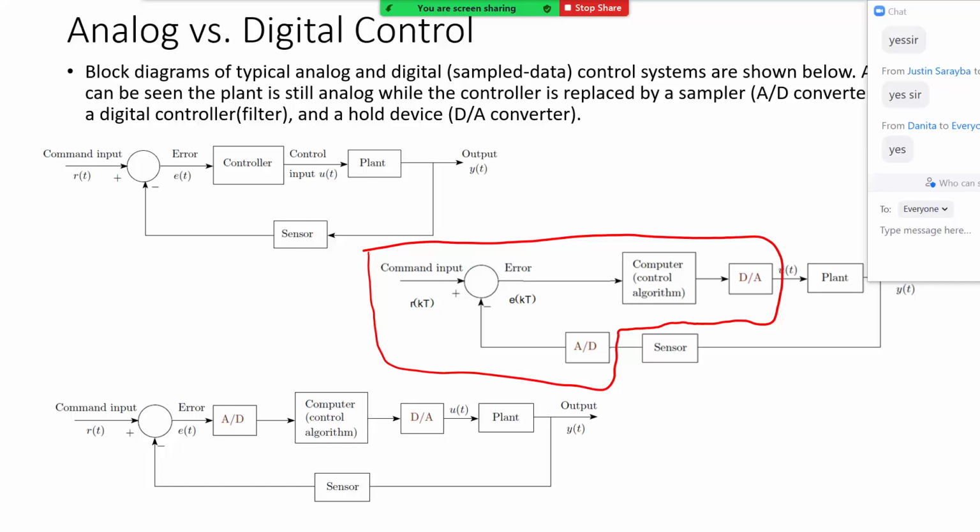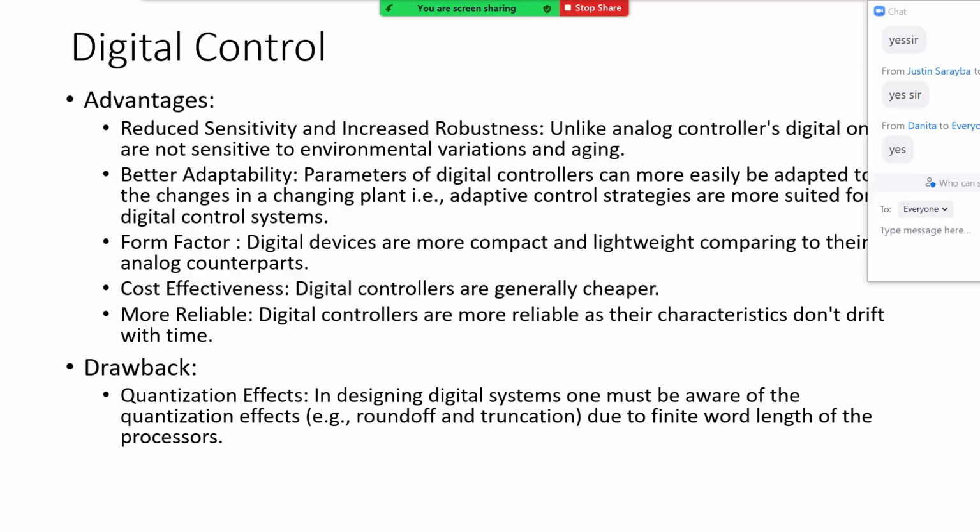And therefore, if the signal happens to be at the exact level, that's great. There is no loss of information. Nevertheless, if the signal is within a range where there is no quantized level that fits it, I'm going to approximate it with the closest quantized level. We'll see this later on, but the idea is, because of that, I'm going to be losing some information that relates to the value of this signal. Okay.